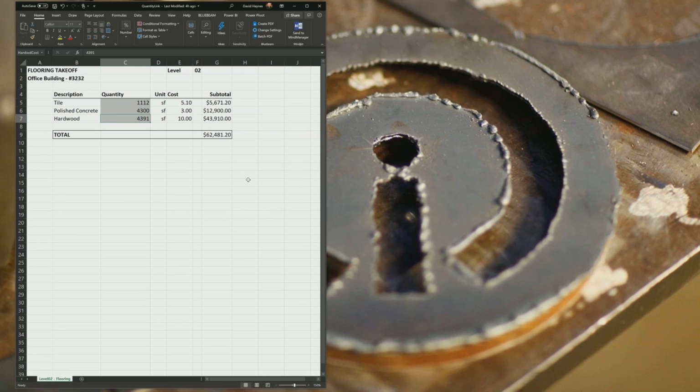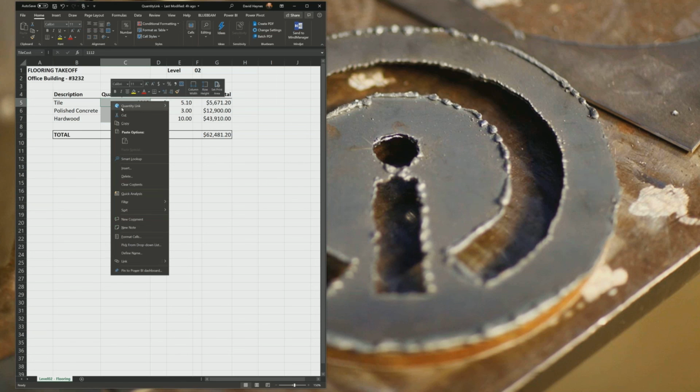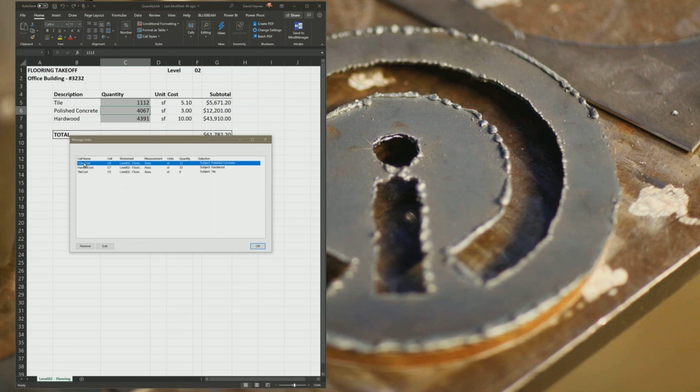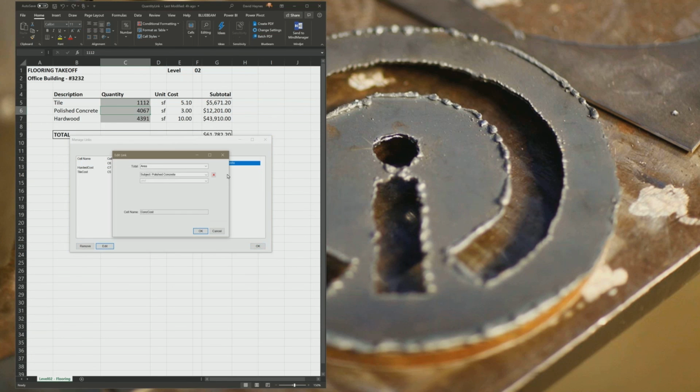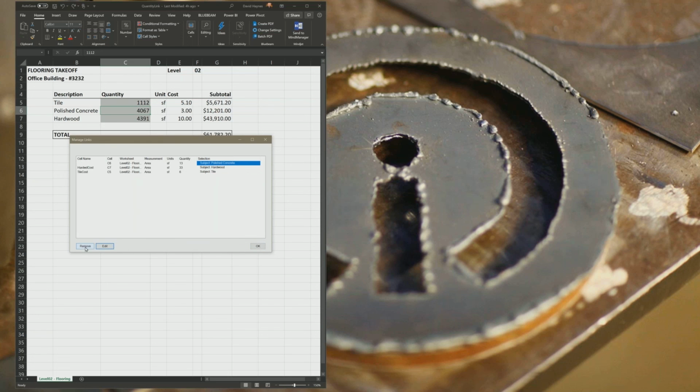And then let's see, can you carry the takeoff markups onto the revised sheet and adjust accordingly? Ooh, that's a good question, right? As I understand it, you may have a version 1 drawing, and then you have a version 2 drawing. There are ways to do that. A couple ways: if you replace a sheet, there is an option to transfer the markups to the new sheet. Or if you're doing a batch slip sheet, there is a way to transfer those markups over to the next PDF. That way you don't have to redo this whole process, which can be quite time consuming.